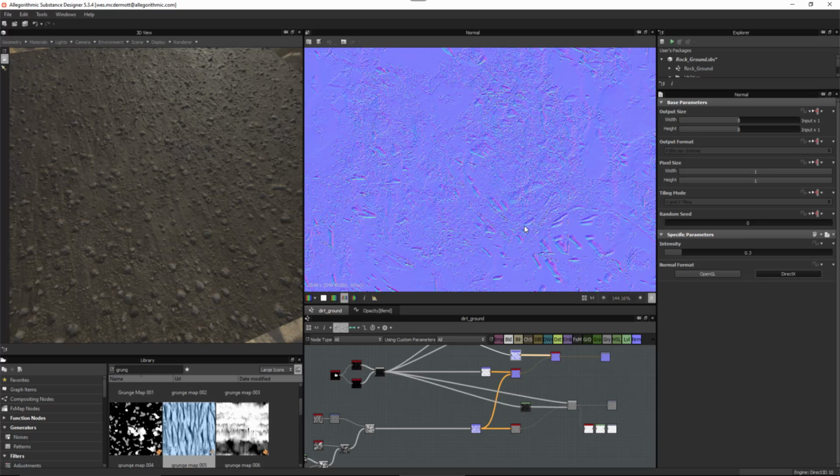So it's almost like we're using it to create the overall silhouette of the object, or the overall feel of shape. The normal map itself is where all the high frequency detail comes in. If we try to use a height map to displace a lot of high frequency detail like this, it's just really not going to go well. So that's why I try to separate these.